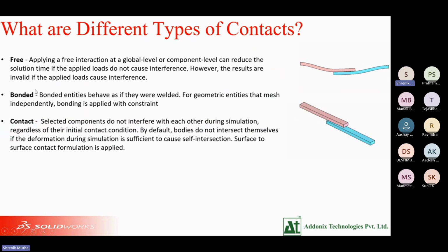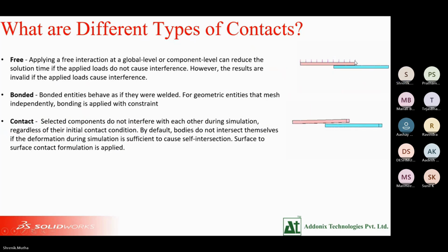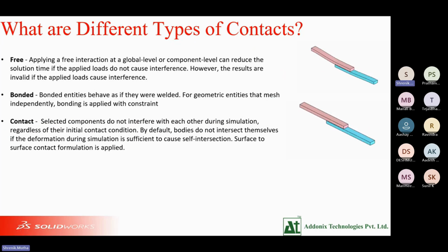Let's start with bonded. Bonded entities will behave like a welded part. Let's say two plates are joined over here. They won't lose contact with each other. They will behave as if they are welded. Next one is contact.